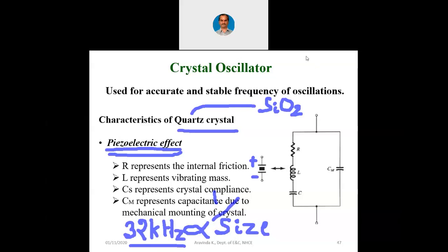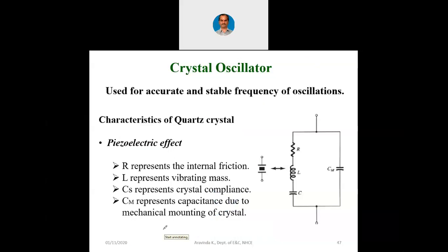So now, what is done in the case of our wristwatches is, this 32 kilohertz which is coming out of the crystal, that crystal is connected as a feedback element to the amplifier. Our feedback circuit will be the crystal only. The amplifier's output is now 32 kilohertz.